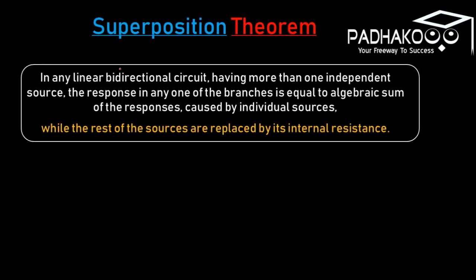Now coming to the superposition theorem. In any linear bidirectional circuit having more than one independent source, the response in any one of the branches is equal to the algebraic sum of the responses caused by the individual sources. Let us take an illustration.